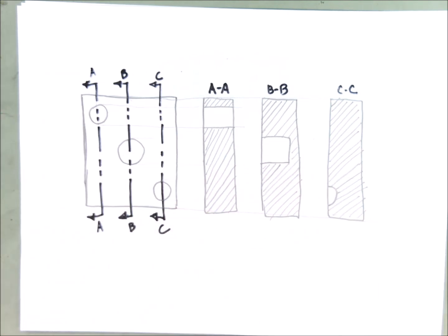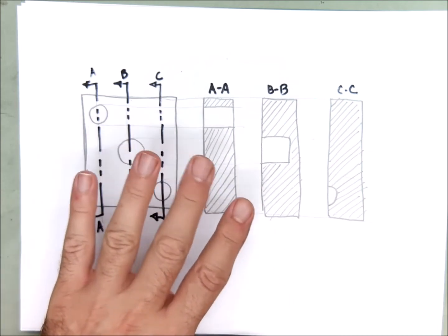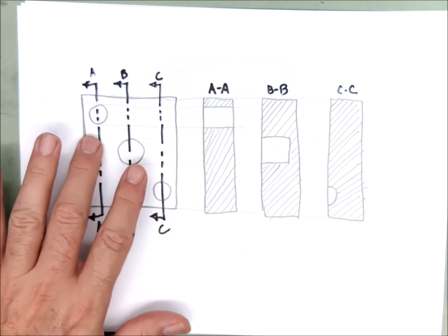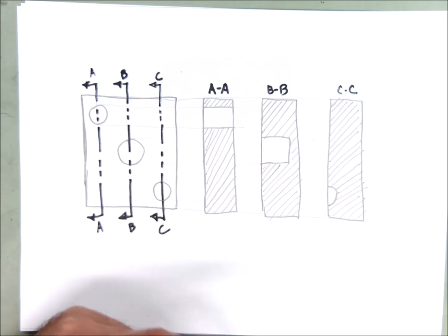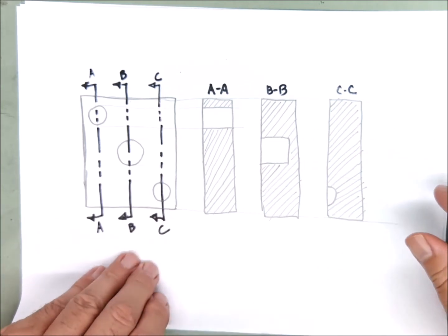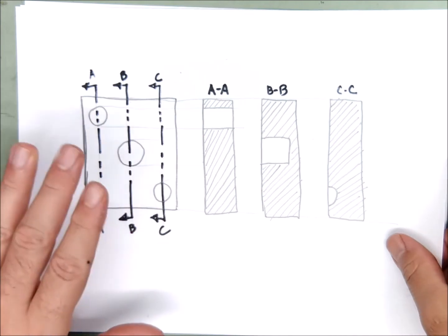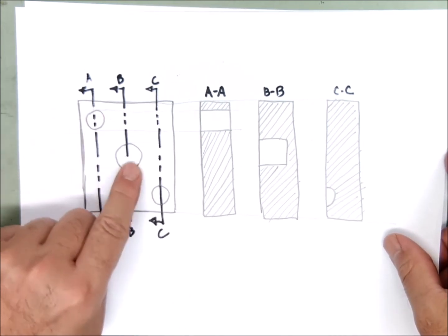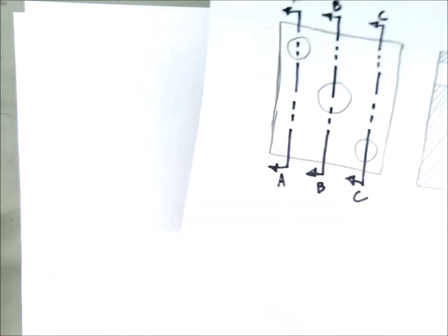Okay, so to avoid having to do all that work and to make 3 cutting plane lines, which is a ton of work, not to mention all that section lining that you're going to have to draw with tools perfectly spaced. Oh my gosh, let's try to minimize the work, right? So when we have a case like this, when we have things that don't line up but we want to show them in section, we're going to make a different kind of drawing.